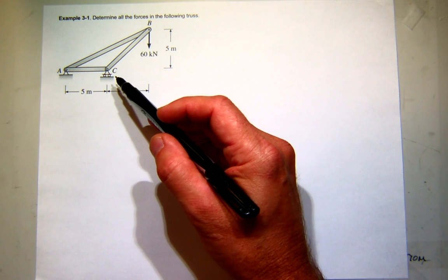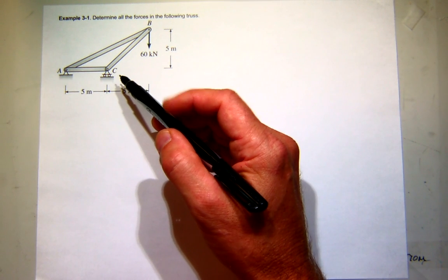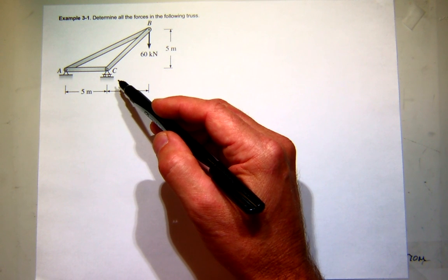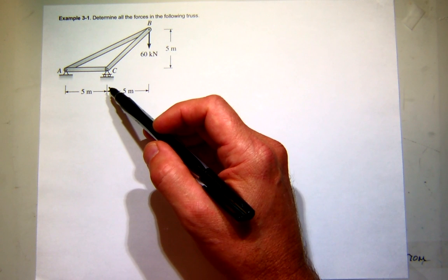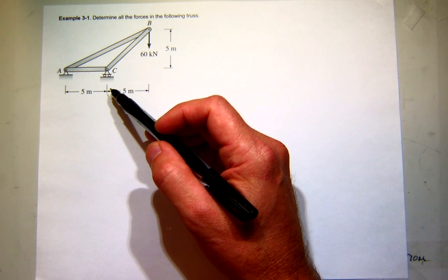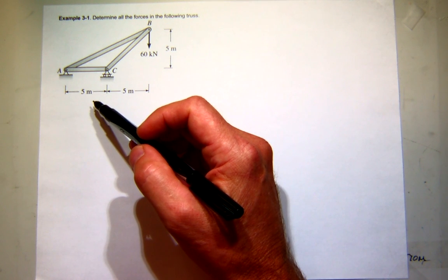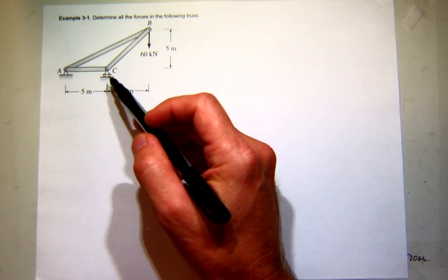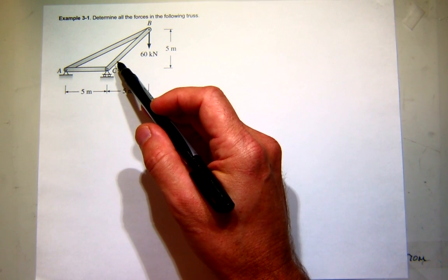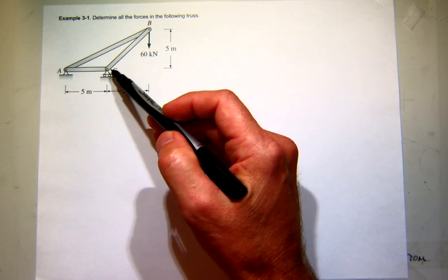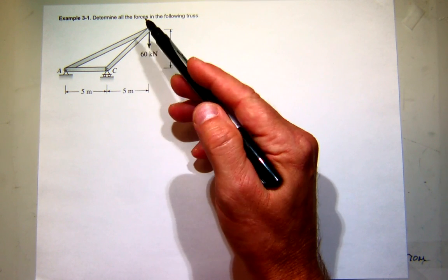Just to connect it with some things we've talked about, is the truss stable internally? Yeah, it's a triangle. There's not much you can do with that. How about externally? Yeah. So we couldn't work an unstable problem anyway, but I just want to make sure that you keep checking on that. Also, is it statically determinate? Yes. We got 3 reactions, 2 at the pin, 1 at the roller. We have 3 bar forces, 3 plus 3 is 6. And we have 1, 2, 3 connections, 2 equations at every connection, 6 equations, 6 unknowns. So we should be okay.